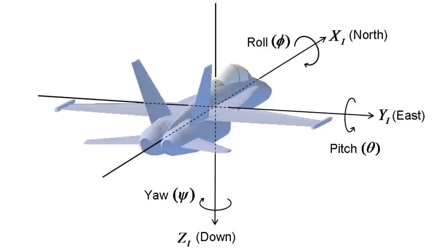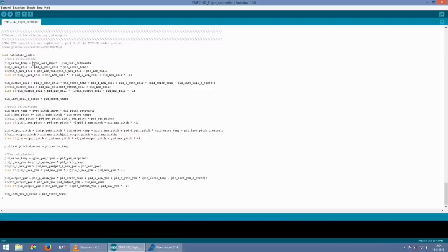This picture that I have shown before represents the roll, pitch and yaw axis of the multicopter. When the multicopter rolls right wing down due to wind or turbulence, the gyro senses a positive roll. When the receiver input is 0 degrees per second, the output of the roll PID controller is positive.